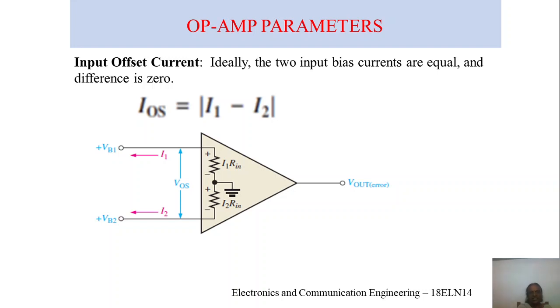However, high gain, high input impedance amplifiers should have as little input offset current as possible, because the difference in current through a large input resistance develops a substantial offset voltage, which is directly given in the diagram. It means that here the effect of the input offset current is clearly shown by this common mode connection.